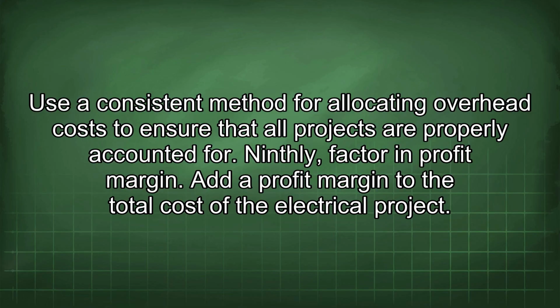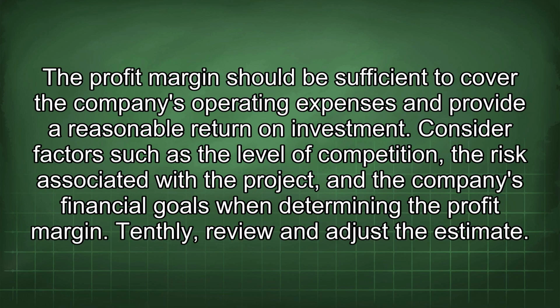Ninthly, factor in profit margin. Add a profit margin to the total cost of the electrical project. The profit margin should be sufficient to cover the company's operating expenses and provide a reasonable return on investment. Consider factors such as the level of competition, the risk associated with the project, and the company's financial goals when determining the profit margin.